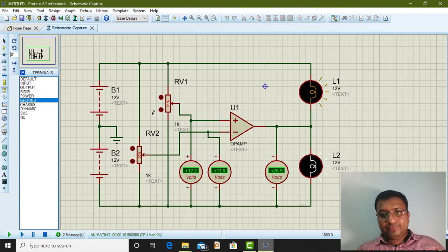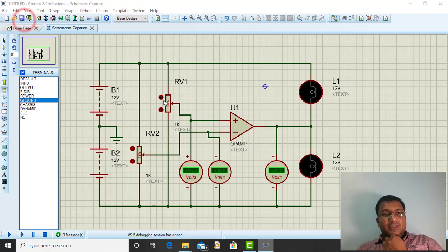Alright, whenever this is less, the output goes to minus VSAT. Look at this, minus 3.01, this LED is on. Alright, so a little change will make the sense. Okay, are you observing the thing? Okay, so this is the op-amp simulation. An op-amp has a plus VSAT and a minus VSAT. So I will stop the simulation and save this particular circuit.